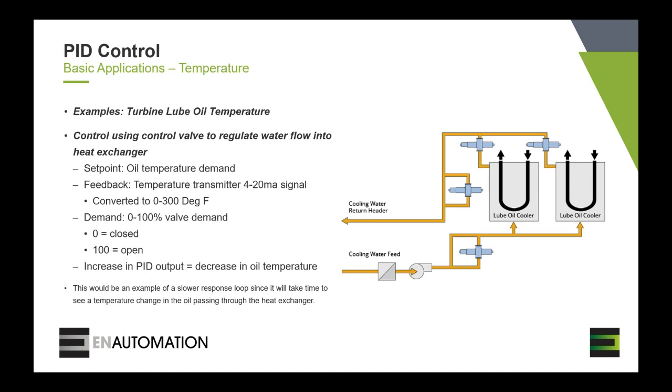So if you set this up to be expecting a response in 10 seconds, then your PID controller is going to continue trying to lower the temperature and lower the temperature, and then all of a sudden all of your efforts will add up and put you outside that stability range, and you won't be able to recorrect it.